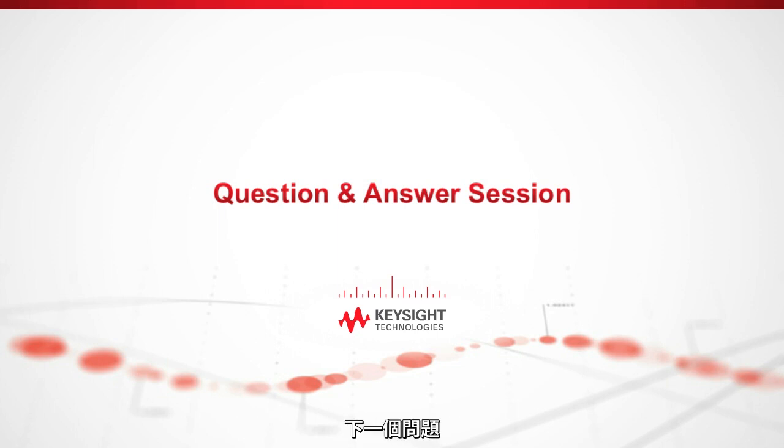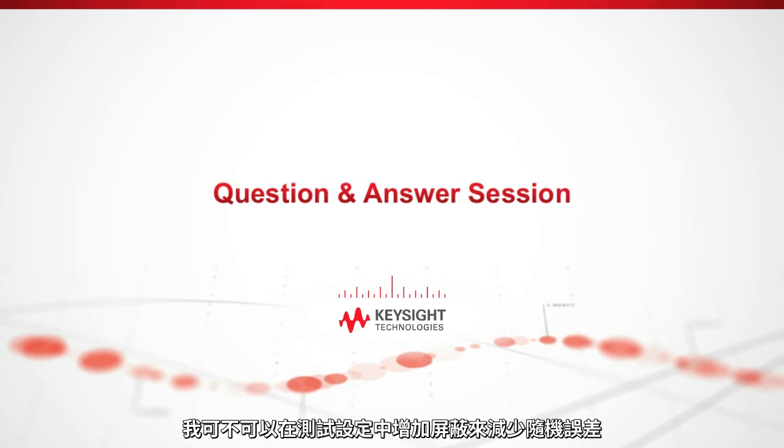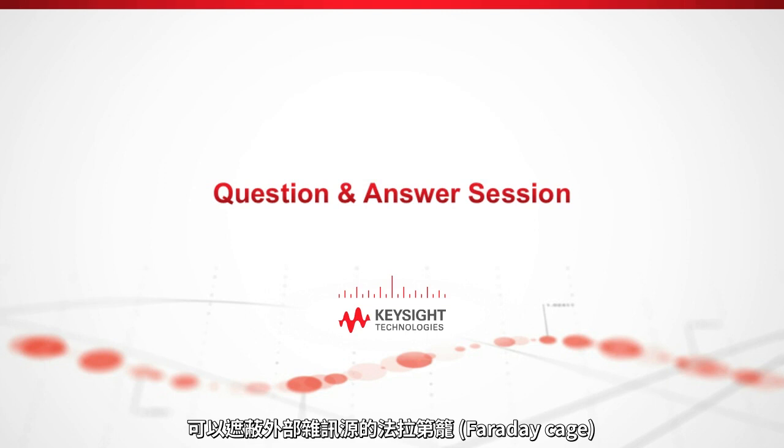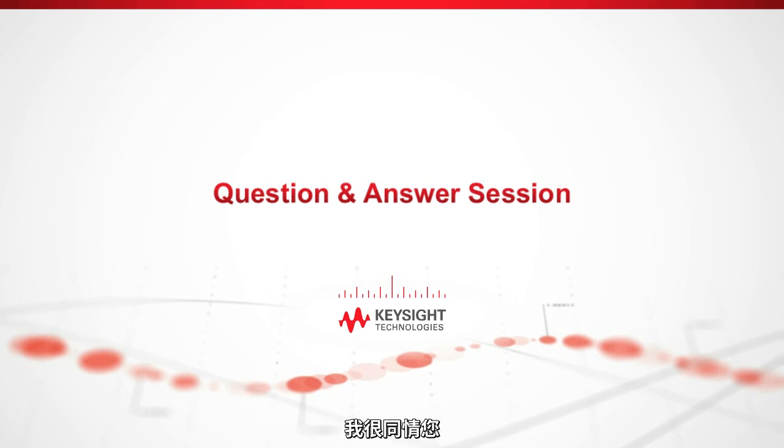Next question here. Is there a way to reduce random errors by adding shielding to my test setup? Yes, there are ways to build Faraday cages that can shield external noise sources. If you're in a particularly noisy environment in your lab, which if you are, you have my sympathies, because that's not the best environment, but it happens. Anything you can do to shield stray radiation and send it to ground is a helpful thing.